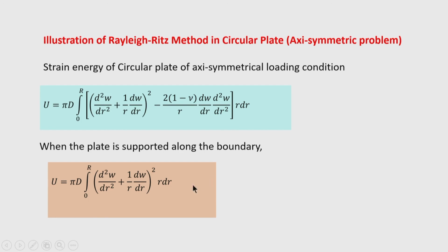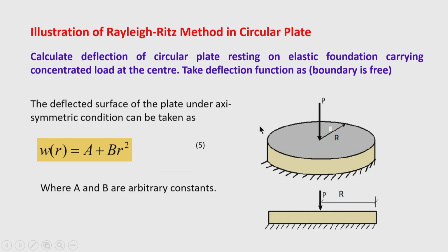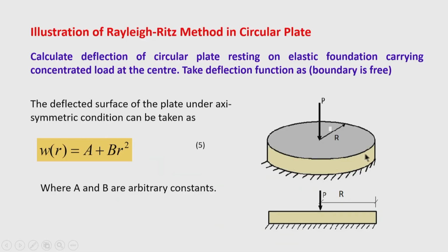But consider here a problem in which a circular plate is resting on an elastic subgrade. Just imagine or idealize a foundation slab, that is a circular footing, for example, a circular footing for a circular column, if somebody wants to construct it. Then this footing, this foundation slab, may be idealized or modeled as a plate which is resting on the elastic subgrade.